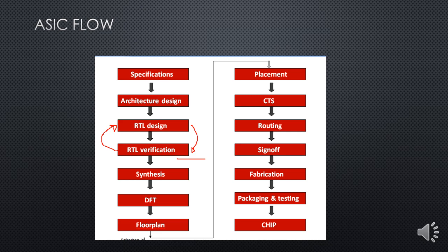At this step, it is the responsibility of the designer to design the code in such a way that we can convert all of his logic to the gate level netlist. The synthesis guy can say whether some of the code he has developed can be converted to the gate level netlist or not.